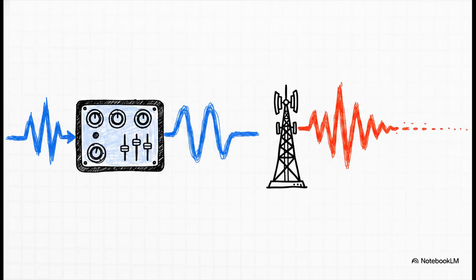But look, governing the airwaves isn't just setting rules and sitting back. It is incredibly tough. The major challenges? Well, for one, as network conditions change minute by minute, systems have to dynamically reconfigure their transmission parameters, like constantly tweaking the modulation scheme to fix error rates on the fly. Secondly, as we push into 5G and start using way higher frequencies, we are fighting a relentless physical battle against path loss. Simply put, those high-frequency signals just naturally weaken a lot faster over shorter distances.